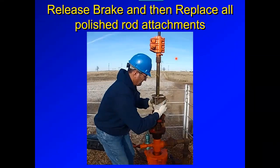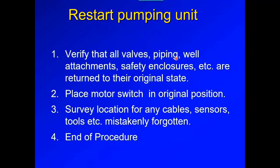Once the stack off tool is removed, we're going to install all the implements and all the accessories that were on before. Lubricator, anything that was on the wellhead before we actually decided to take the measurement. Now, I'm going to verify that all valves, piping, and everything is returned the way that it was. I don't want you waking up in the middle of the night thinking, did I open that valve? Because I know we all do that at times.